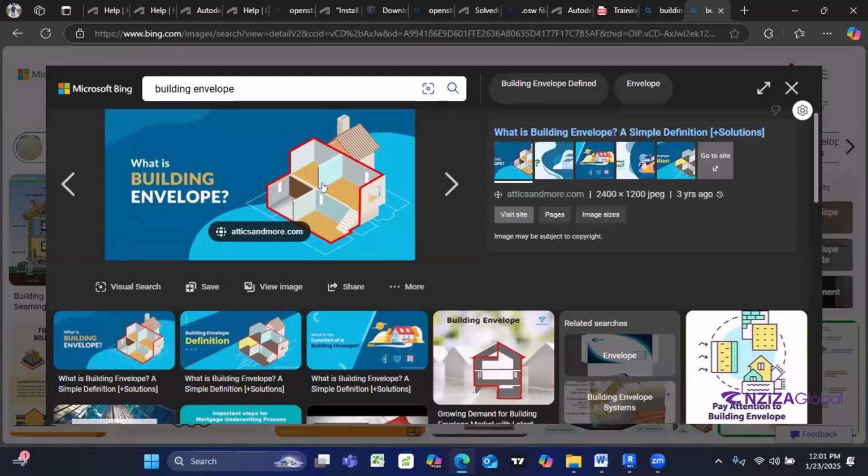Each material of the building envelope has its assigned U value. The U value will mostly be used in load calculation. Each material has its own U value. The U value is the ability of the material to transfer heat. For example, the heat transfer capability of metal is different from wood. The heat transfers faster on metal than on wood. So its U value will be different.